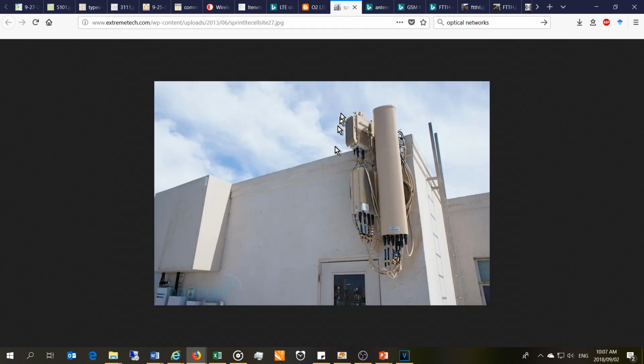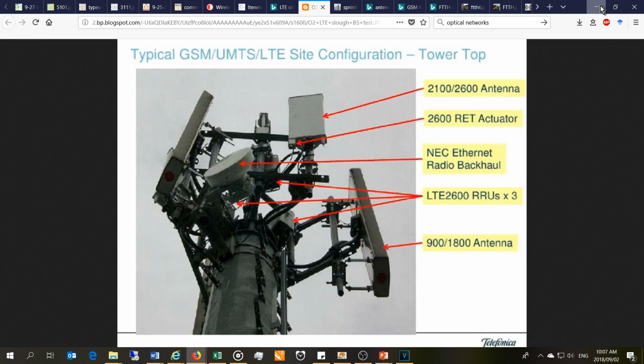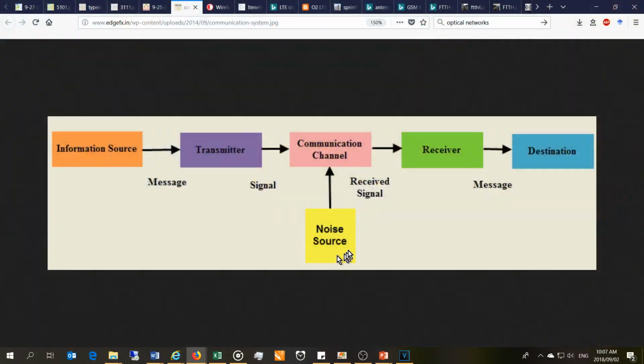So all of these things interfere with the original signal. So all of that adds noise. That is why this diagram shows a noise source. It just means that the environment often adds some noise. Maybe you ran your cables next to some power lines or some high voltage or high current carrying cables, or there were industrial machines, or people were using drills or contactors. Well, that will also add switching noise, or even some spurious response, spurious spikes to your communication.